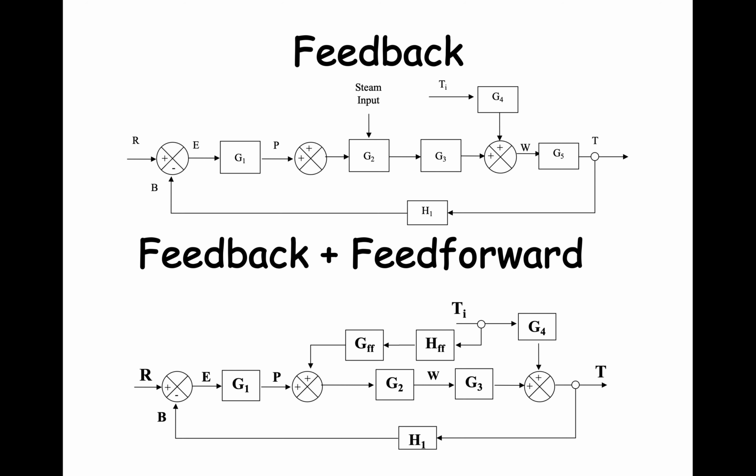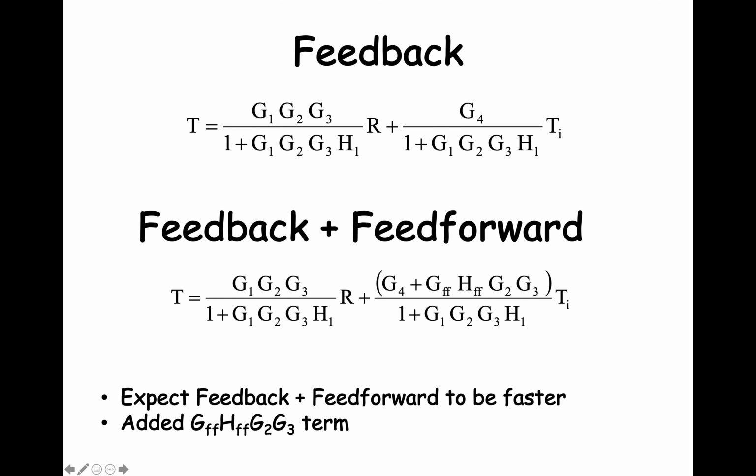You can see where the feed-forward elements GFF and HFF are added, and they use the inlet steam temperature to modify the signal to the actuator G2. Here are the two overall transfer functions.